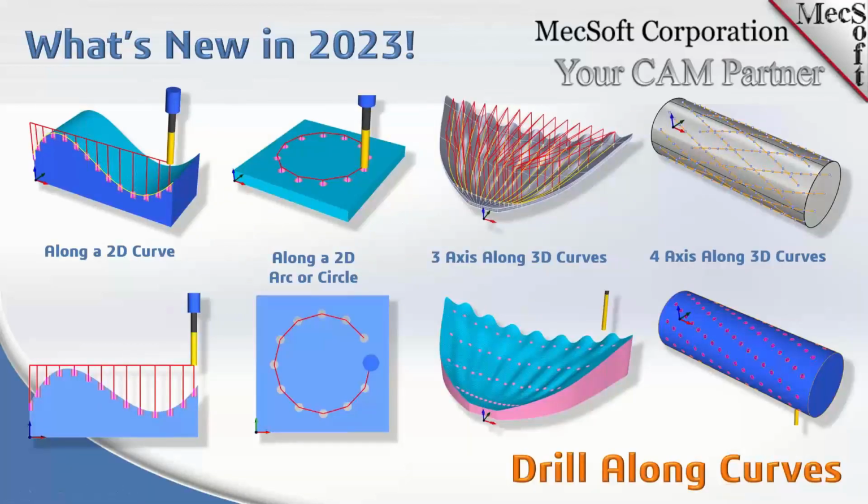Now, here you can see the different drilling along a curve command. We start in the top left. You can drill along a surface edge curve. In other words, you create a curve from a surface edge, and you can drill along that curve based on how many drill holes you want to make, or how far distance they are apart, and it will calculate that along the curve.